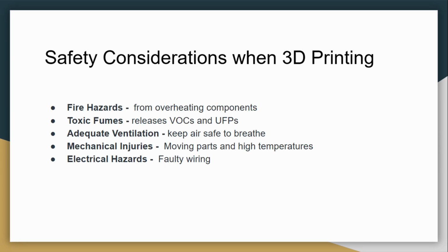There are potential risks associated with 3D printing. The main things to be aware of are fire hazards. Printer heating elements can get stuck on high, which could cause a fire. This is called thermal runaway.